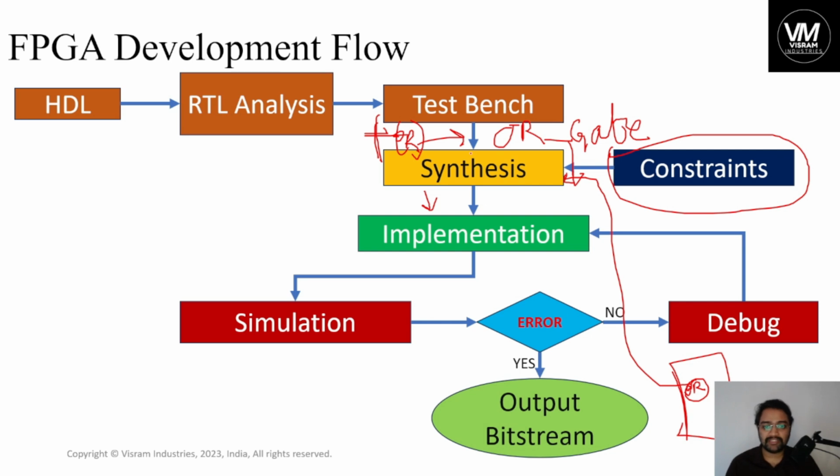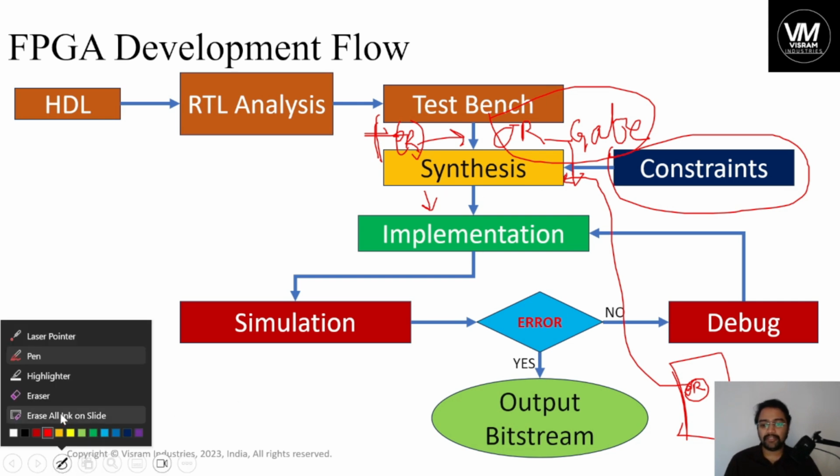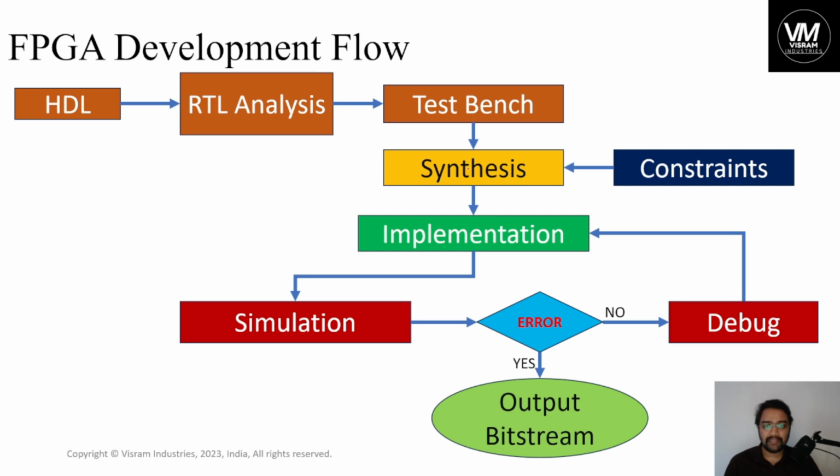So what synthesis is doing is taking the function or script that you have written and mapping it into the physical environment, into the gate level. Hence after synthesis you will get a gate level netlist, and we will be using all the gates. Then we will be implementing the design with all the gates and ports, and in the implementation, you will be doing IO planning,